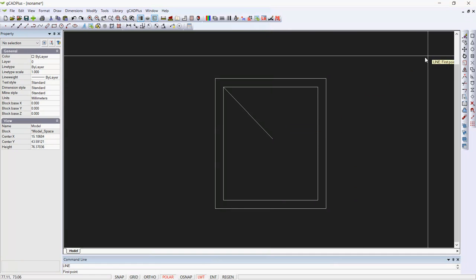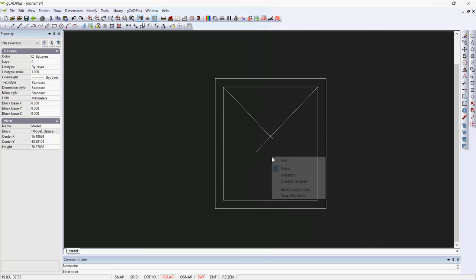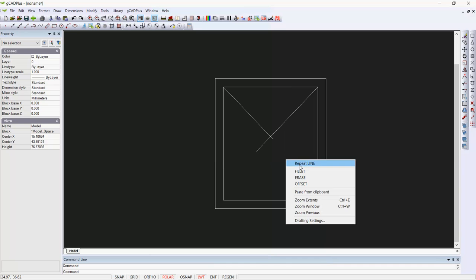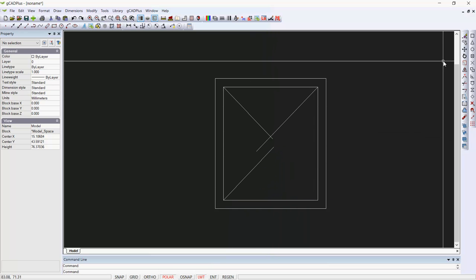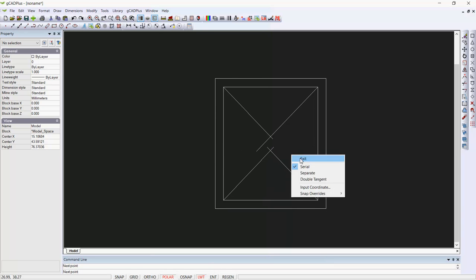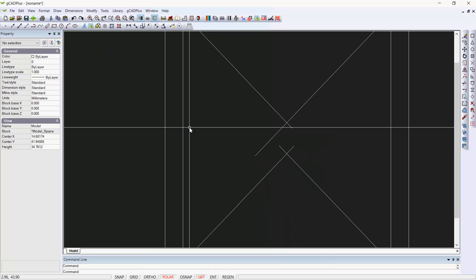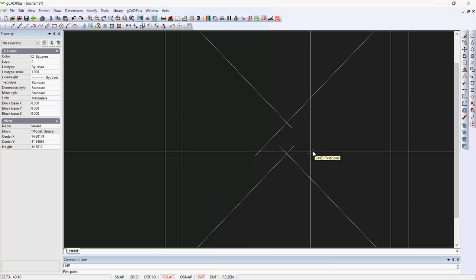So I'll repeat the line, pick up this one here, come through there like so, and repeat for the area down here, although I could have mirrored it. You'll notice that I'm making sure I go in enough distance so that the lines cross like so. Now I'm going to draw another line, right click, pick up line from an intersect there to an intersect here.